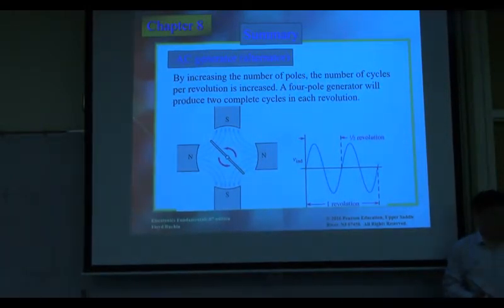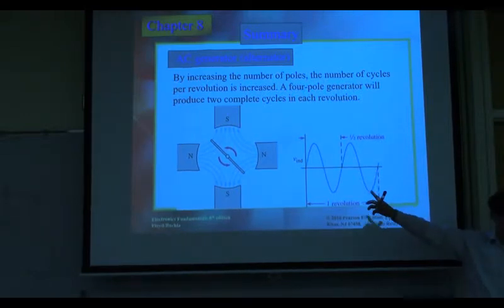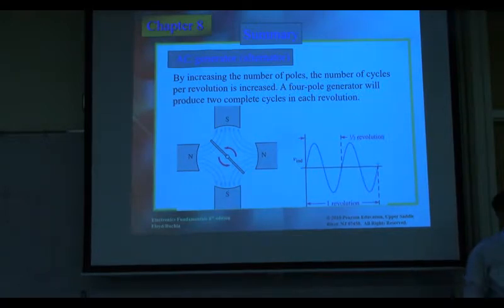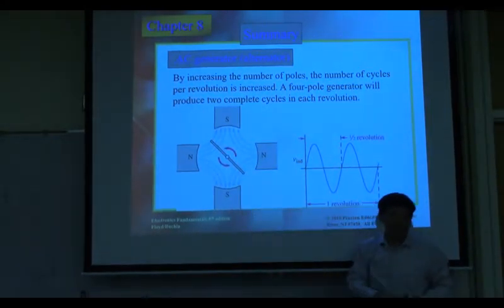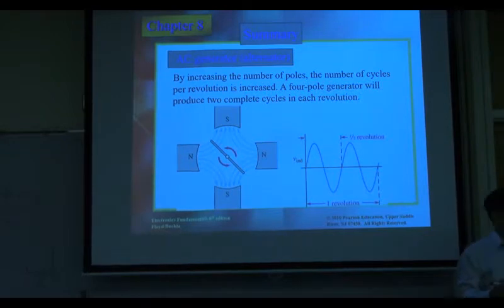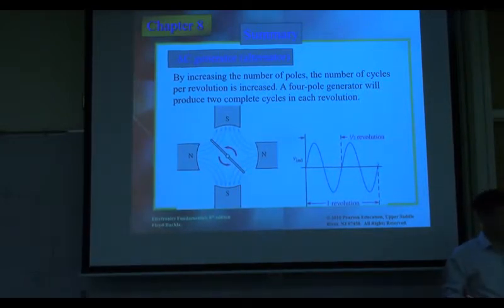But the most industrial, the real actual ones, have more than 2 pairs. Actually, they use 3 pairs. So that's why sometimes it's called 3-phase. Anyone has worked with any motors or something? Yes, a 3-phase motor, right? So why is it called 3-phase? 3-phase means we have 3 pairs of this. Here we have 2 pairs, separated by 180 degrees. And if you have 3 pairs, each one will be separated by 120 degrees.